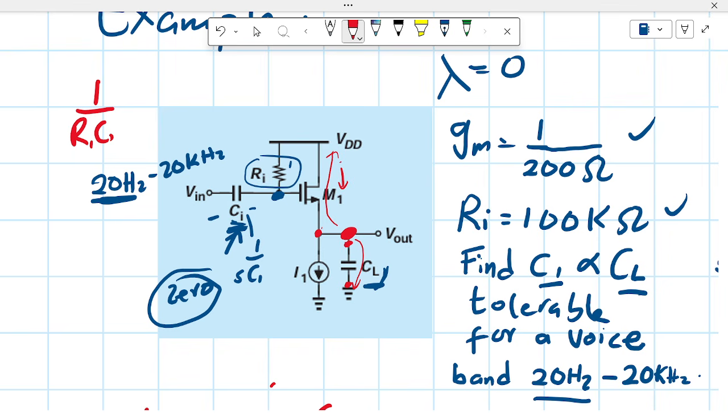Low frequency signal gives an open circuit, whereas a high frequency signal would short circuit this to the ground, which would mean the output goes to 0. In that case, this node is rather introducing a pole, because as the frequency increases, the output reduces.